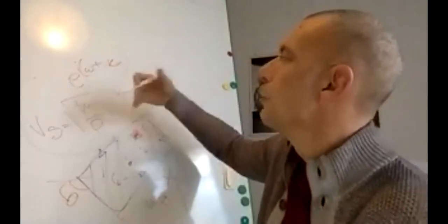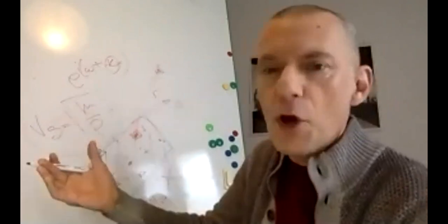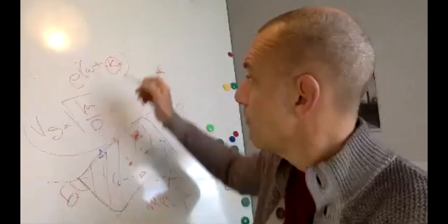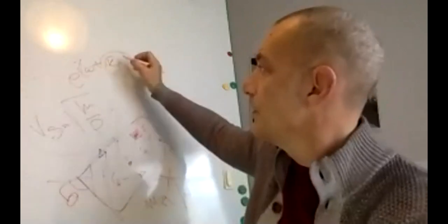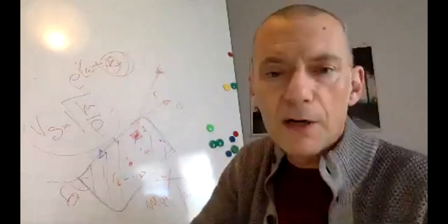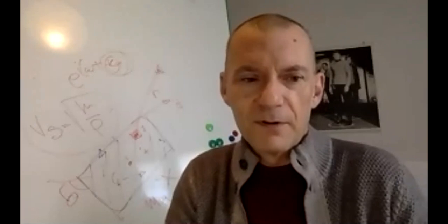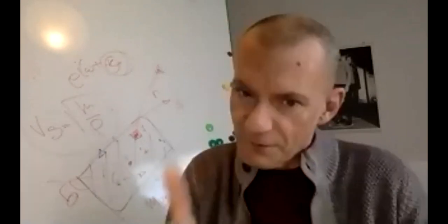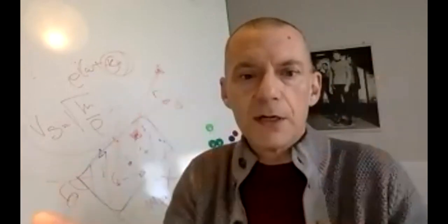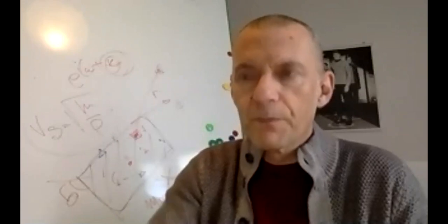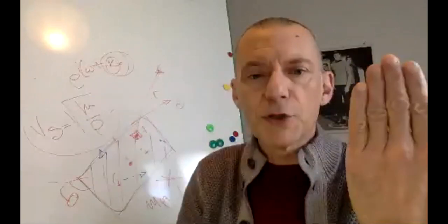a typical wave that is propagating in some direction with a wave number k, if velocity is complex, k will become complex. And if it is complex, then we will have the real part that is the propagating factor, but the imaginary part will be the damping in the propagation. That's the idea, and that's the only idea that is necessary for you to take home. That will be necessary, but not sufficient for the exam, of course, because for the exam, you will need to know also what we're going to discuss today. But that's the idea: moving from Hooke to the viscoelastic domain, complex moduli, complex velocity, complex k, and we have a propagation and attenuation factor.